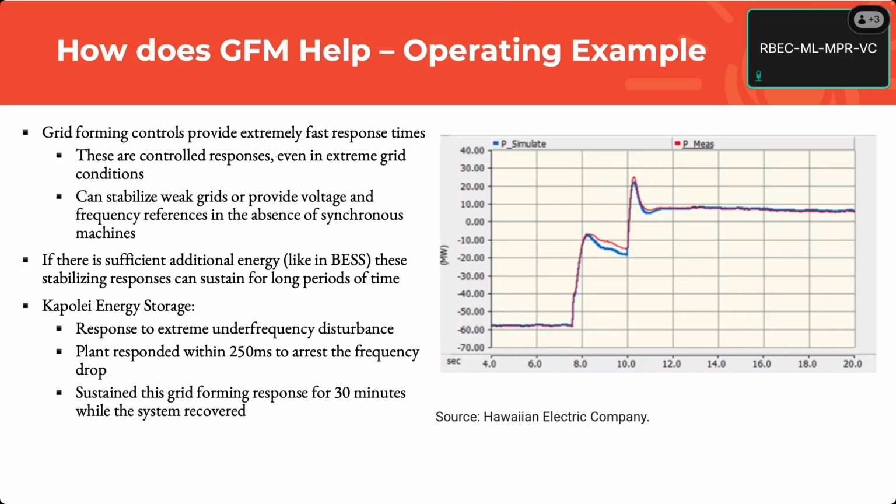The same way that synchronous machines all can work together because of the physics that's holding everything together, they're stable in the small signal world. Grid forming can do the same thing, okay? And it's stable because it's not fast. The reactions are fast, but the controls are not, okay? Perfect. But we'll talk a lot more about it.